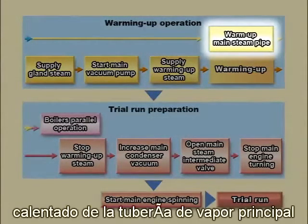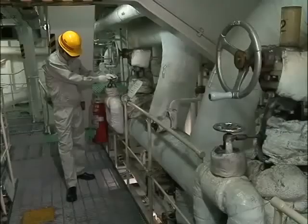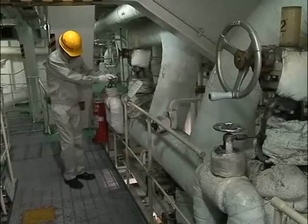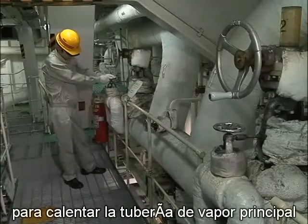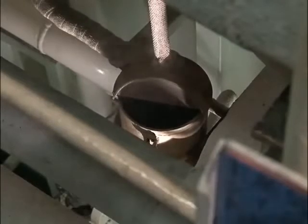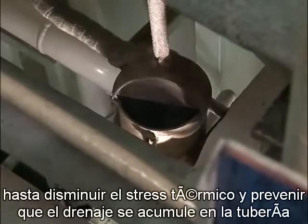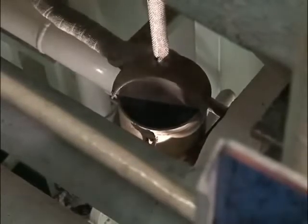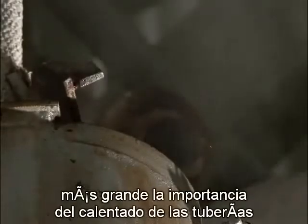Warm up main steam pipe. Pipe warming up refers to the operation to warm up the main steam pipe leading to the main engine that's in a cold condition while in port, and to lessen thermal stress and prevent drain from accumulating in the piping. The higher the temperature and pressure and the larger the pipe diameter, the greater the significance is to piping warm up.